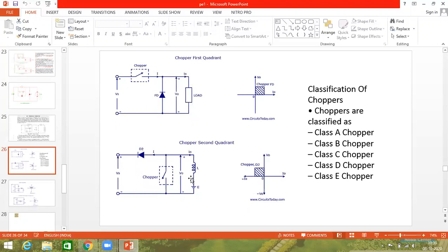Okay, we'll see in detail also animation. Now, what is this circuit? How to explain? This circuit, we have to give the explanation when the chopper is on. Case 1. When the chopper is on and the back EMF of motor is greater than the supply voltage, this circuit operates only at one condition: when the chopper is on and back EMF of the motor is greater than the input voltage. So now here only one statement we can write.